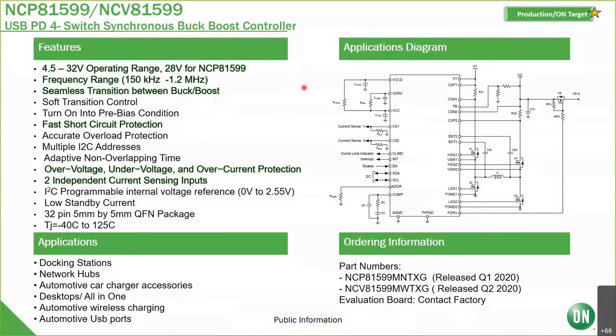And we use this for a lot of our USB products, and I covered that two weeks ago. I did USB, so feel free to download that and watch the recording. And I have a lot of information on this buck boost there, but I wanted to touch on it here. And it's got protection for over voltage, under voltage, and over current protection, and then 2 independent current sensing pins as well. And that comes in a 5x5 millimeter QFN package.